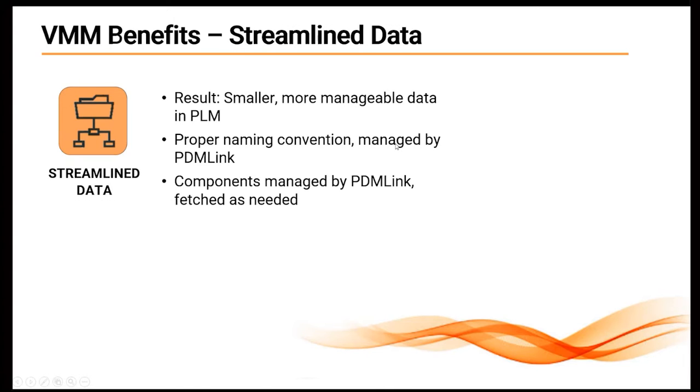So the second thing is that the data is much more manageable. In PLM, we only have the parts or the sub-assemblies, the things that are not changing, and they will come together. Naming convention, we can manage it however the PLM system allows. For example, you can create new part numbers. In the example I showed you, the back plate has to receive some holes or some cutouts. Therefore, it really becomes a new part number, so we are going to manage that and create them.